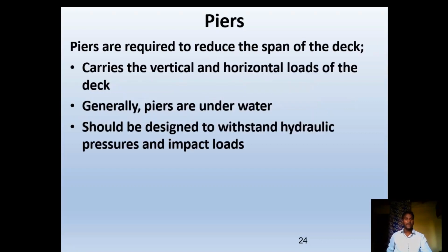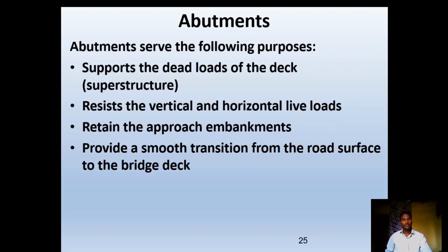Piers. Piers are required to reduce the span of the deck, and carry the vertical and horizontal loads of the deck. Generally, piers are underwater, and should be designed to withstand hydraulic pressure and impact loads. Then abutments serve the following purpose: support the dead load of the deck, superstructure, resist the vertical and horizontal live loads, retain the approach embankments, provide a smooth transition from the road surface to the bridge deck.